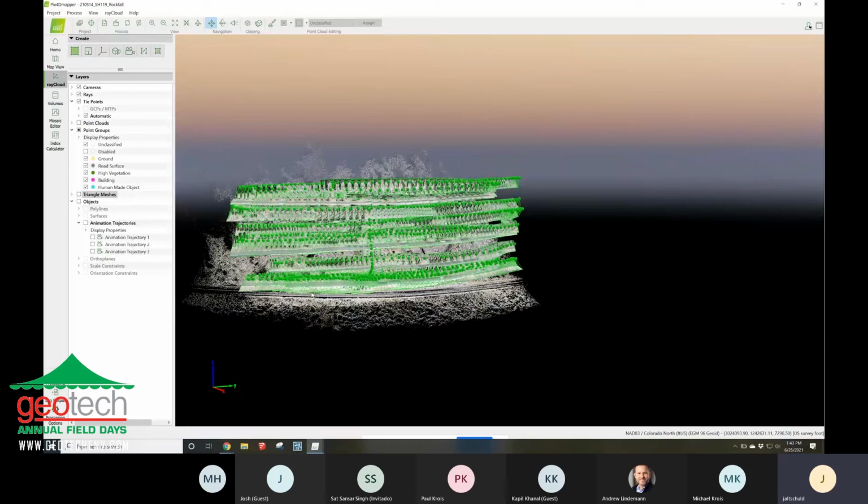Basically where they are, it's very common. The entire country has a fairly high resolution data set. So they have a good data set that they can import and say, okay, make a route off of this. We have, depending on what county you're in, you might just be SRTM, which I'm trying to remember the resolution, but I want to say it's like 50 meters or something. So basically, if you think of the Earth, it's split into 50-meter chunks. And so every 50 meter by 50 meter, you average the elevation, it thinks that's the elevation for that entire area. So something where you need to be within 30 to 80 feet, you're going to either be way too far away or you're going to fly into the side of the cliff.